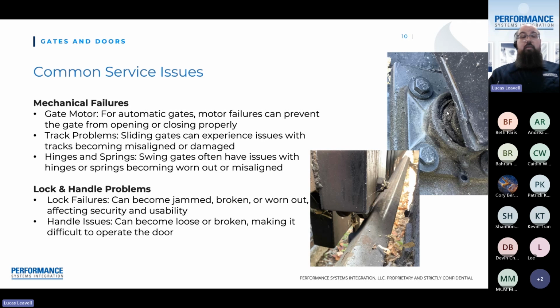You do that often enough, the bushing will change shape. When it starts to change shape, that opens up these gaps that are visible right here. And that means the gate will no longer move properly. As the gate begins to move, it creates vibrations, which create this. The bottom of the pin is now prying away from the gate.